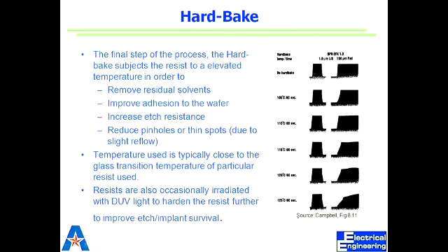If I had this opening for etching and I removed whatever was there, the silicon all the way, this would result in a small pit at the surface. So that will tell me the resist at that point was not completely intact. So there was a pinhole. The defect is too small, that even an electron microscope would find it almost impossible. I'm not saying my electron microscope cannot look at small features, but you don't know where to look, unless those pinholes are everywhere.